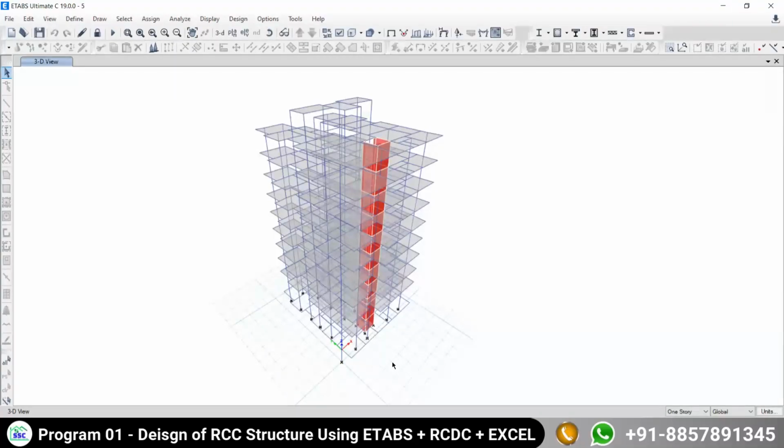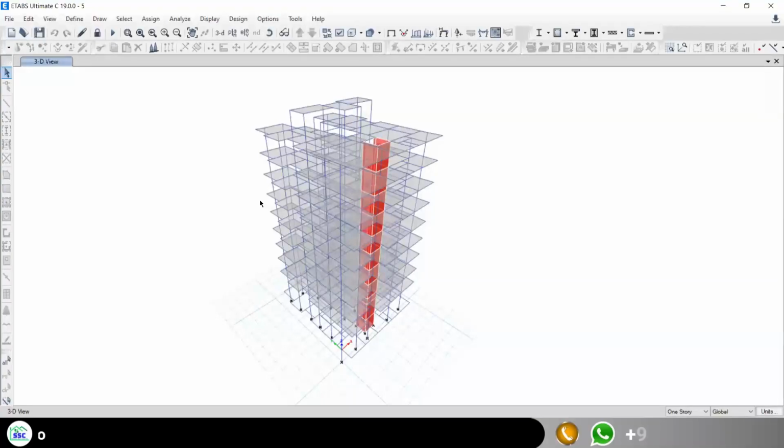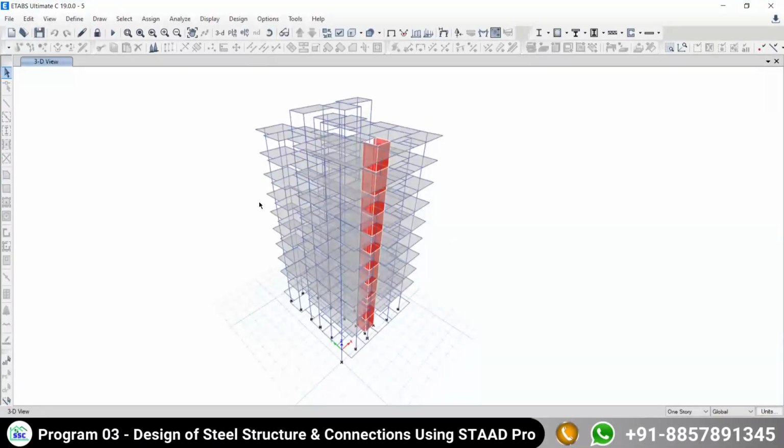Okay, so then what is the solution to this problem? Suppose next time I have to start a steel structure, so I need to have the basic definition of a steel structure. So here the problem for me, I have saved the file of this model. Some of you may suggest that go to any steel project and save the properties of the steel project. Am I right? Yes, sir. Yeah. So actually, in ETABS software, at a time, you can save the definition of one model only.